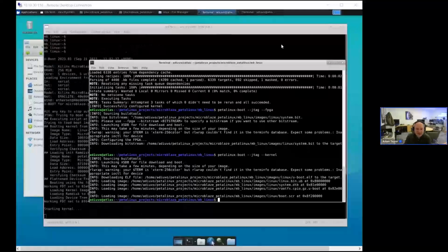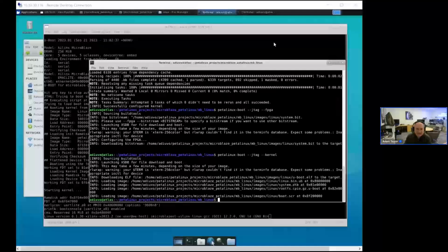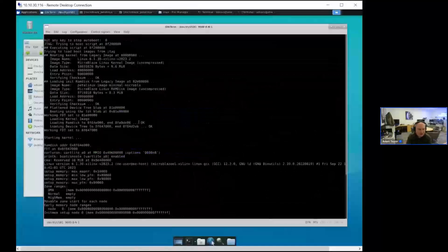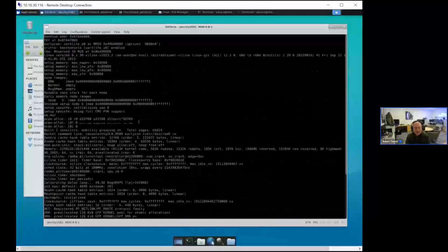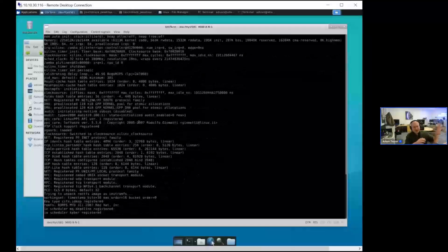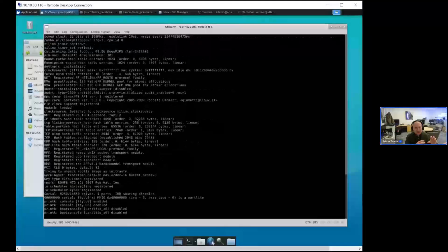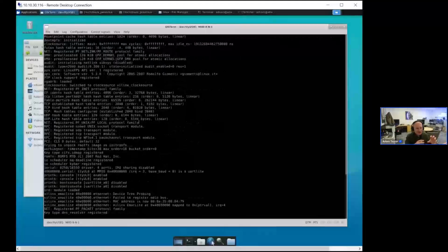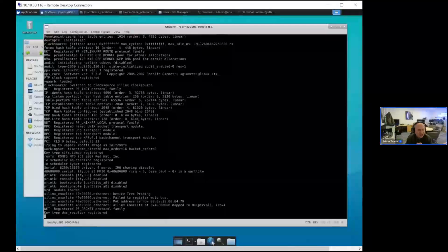So what we can see here then is that it's now starting to run through. We've now got the PetaLinux stuff up and running. Jason, DevMem will work fine, but if you remember back to my talking in the slides earlier about the virtual memory and the memory management unit, DevMem is kind of just punching a hole straight through that, so it can cause a little issue at times.